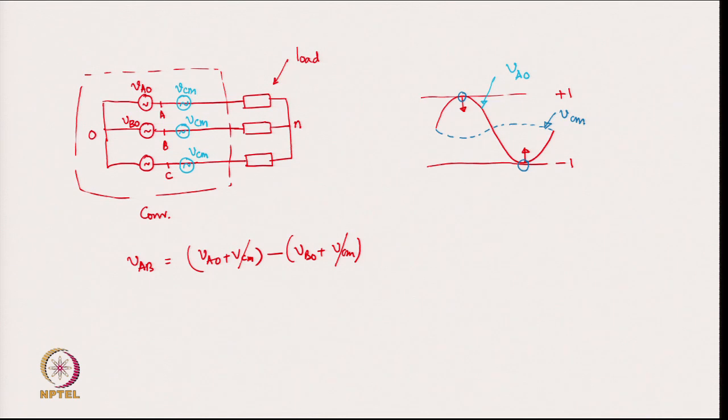So, although we can push the A phase down, we will be pushing the B and C phases up and beyond their +1 and -1 limits, which is not acceptable, because they will go into the over-modulation region. So, adding this VCM as the fundamental is not allowed. So, this will not be possible to do.